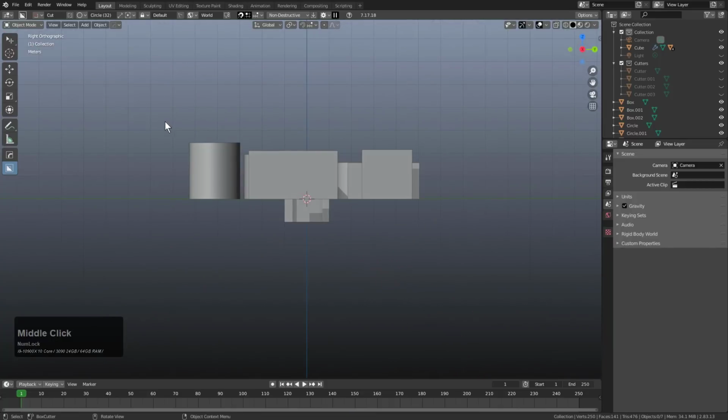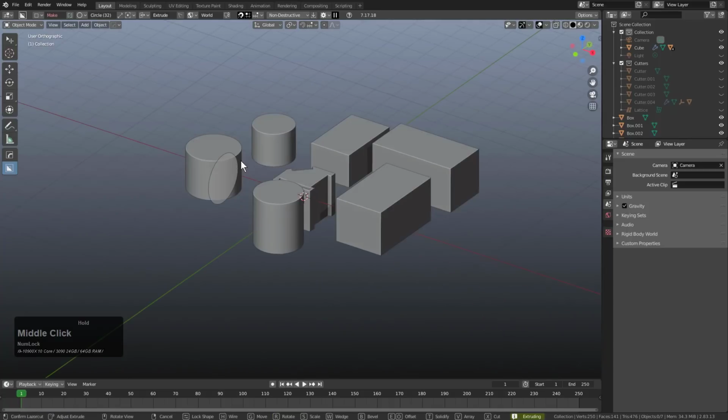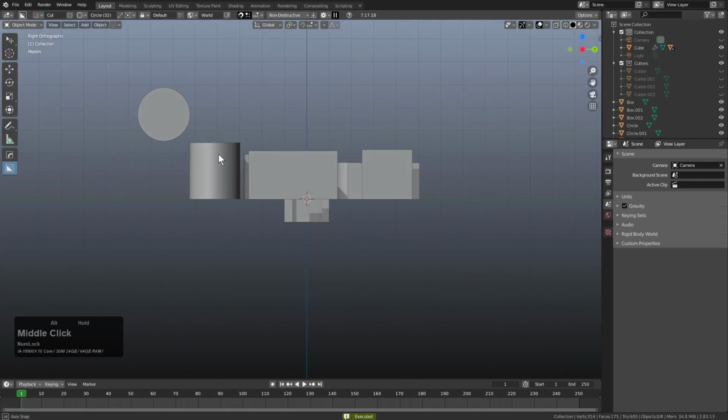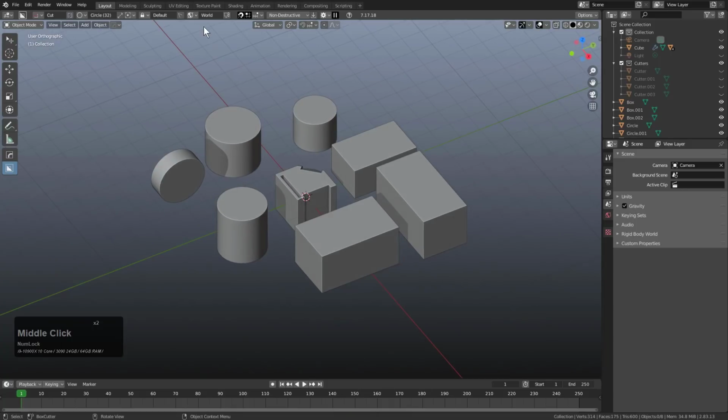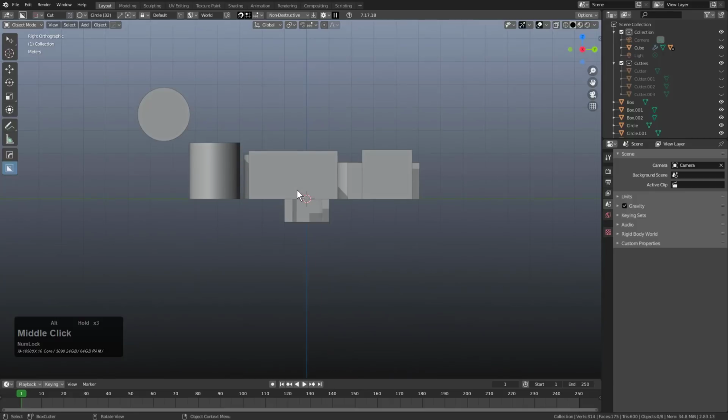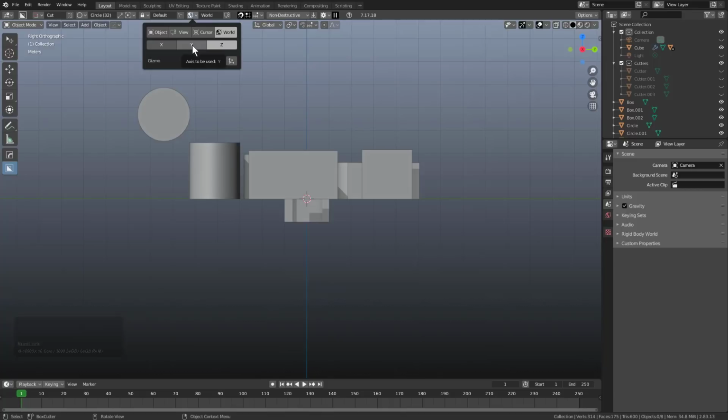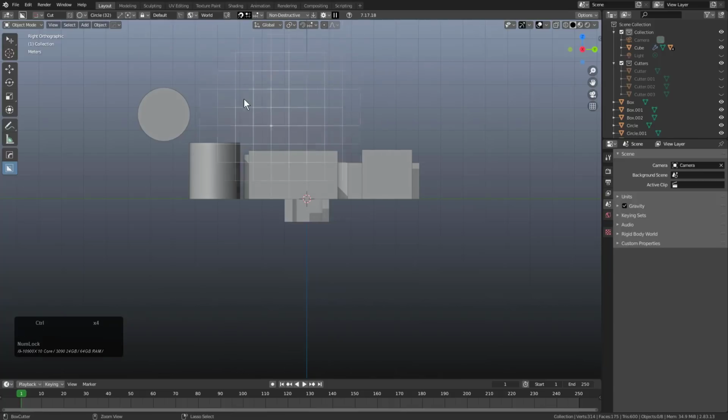However, if we begin drawing from the side, we have it set up where you can begin drawing from the side axes, but when you bring grid into the mix, it begins to get more complicated. Because our world is set to Z, that means we'll only see our grid on the grid floor, but if we look at it from the side, we don't see grid at all at this point, and that's because we need to change our orientation method to be using Y. So now that it's on Y, it's not showing up. We have to go to X, and now we're able to see it on X.